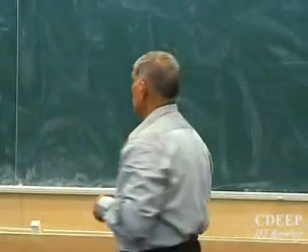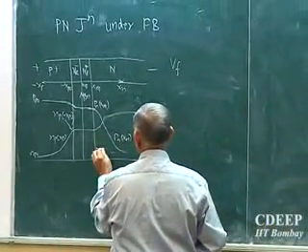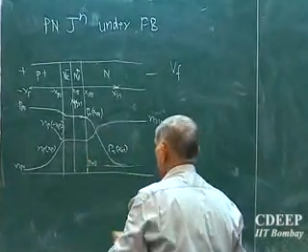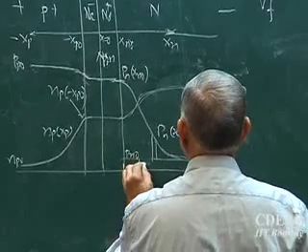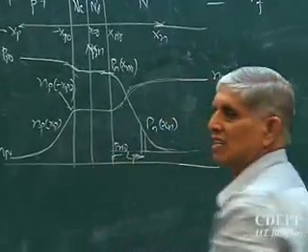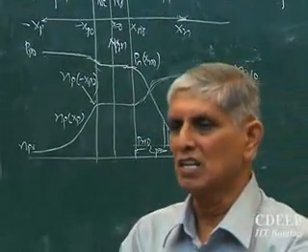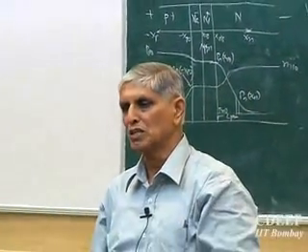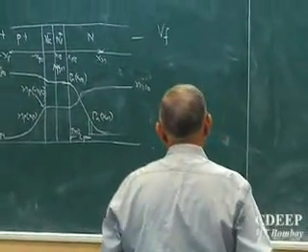So it will go from its Pn(XN0) value towards its Pn0 value, and somewhere here, let us say this distance, 66% of this will be called the diffusion length, up to which the effect of diffusion will be stronger, and finally carriers will decay down due to recombination back to their equilibrium value. The equations we can write for this.